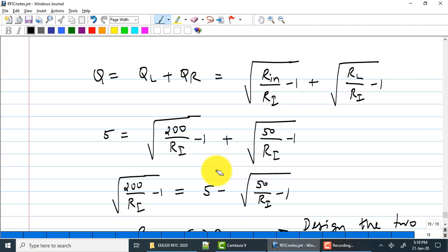Number two, what we have not discussed so far, we have assumed that the components are ideal. If they were not ideal, imagine now that L1 and L2 themselves have some series resistance. How are you going to build an inductor? You are going to wind a wire around a magnetic core. On the integrated circuit, you do not have a magnetic core. What do you do if you don't have a magnetic core? How do you build an inductor if you don't have a magnetic core? You wind it around a non-magnetic core. That's all. The magnetic core helps you because it has a mu R.